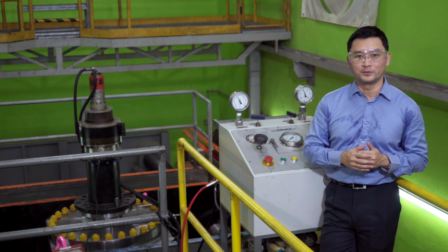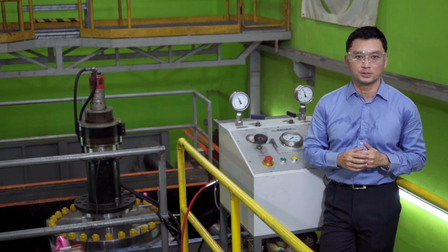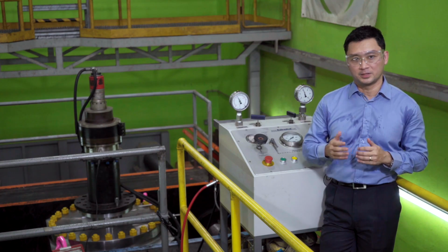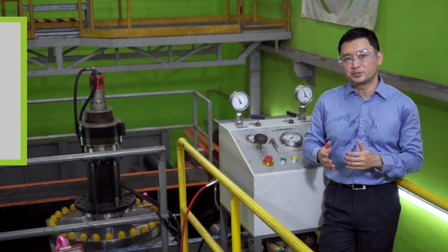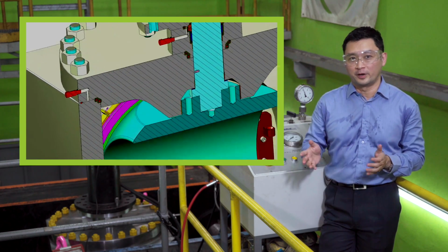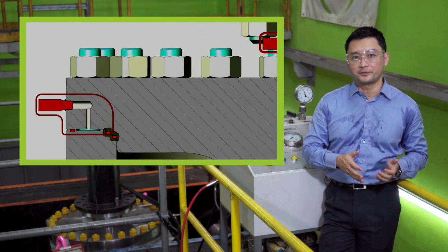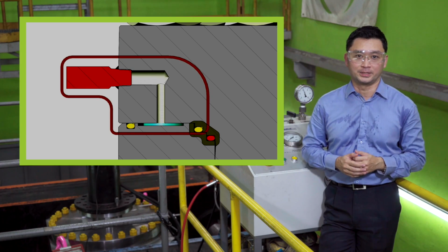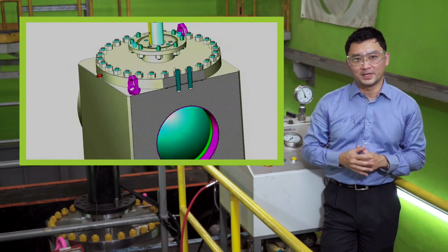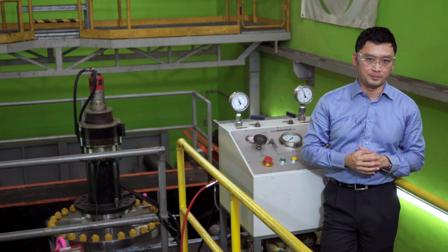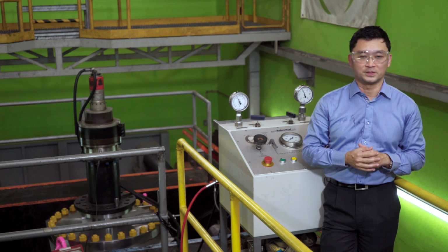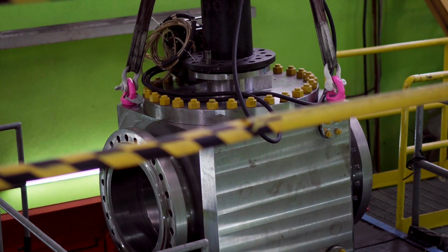Of course, this confers a significant amount of advantages for our clients, especially in terms of monetary and time cost to the project. This feature built into the valve allows the testing of the environmental seals wherever the valve goes, both in the factory and outside of the factory. Also in situ, where the client installs the valve. And when all of the tests are done, all the ports will be plugged and seal welded. And this test allows us to ensure that the seal welds are of a high integrity.